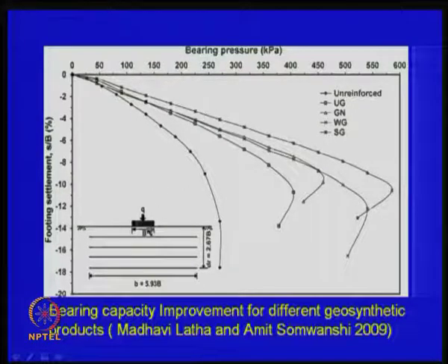This is in a simple plate load test like this, where you apply some load on a foundation, say, at laboratory scale. Actually, this is a laboratory result. In fact, in our institute also we have done a lot of work. This is a typical result. We also published a number of papers along these lines from the Institute of Science, where we can clearly show that bearing capacity improvement is possible by using some sort of reinforcement.